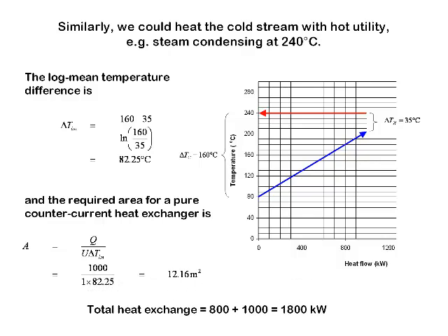So, overall, we have undertaken 1,800 kilowatts of heat transfer. We've got one heat exchanger with 800 kilowatts of heat transfer in order to cool down our hot stream. We've got a second heat exchanger with 1,000 kilowatts of heat transfer going on in order to heat up our cold stream. And these two heat exchangers have between them a total area of 23.15 meters squared. So that's our base situation.